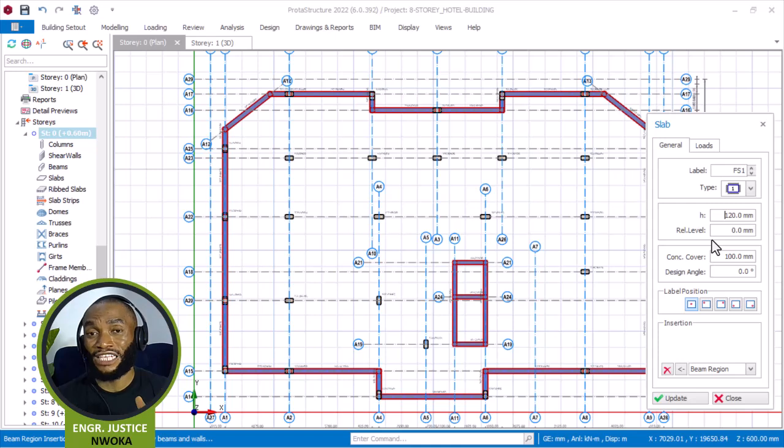Okay, that's fine. So let's now begin with what we have for today, which is the slab raft, level 2, stage 2. With this, we will now input the slab thickness. For slab raft, the thickness, just as you know, you are meant to assume your thickness, but before you assume, there must be a minimum, just like normal slab, where the minimum slab thickness is 150 if you are using UK or European code.